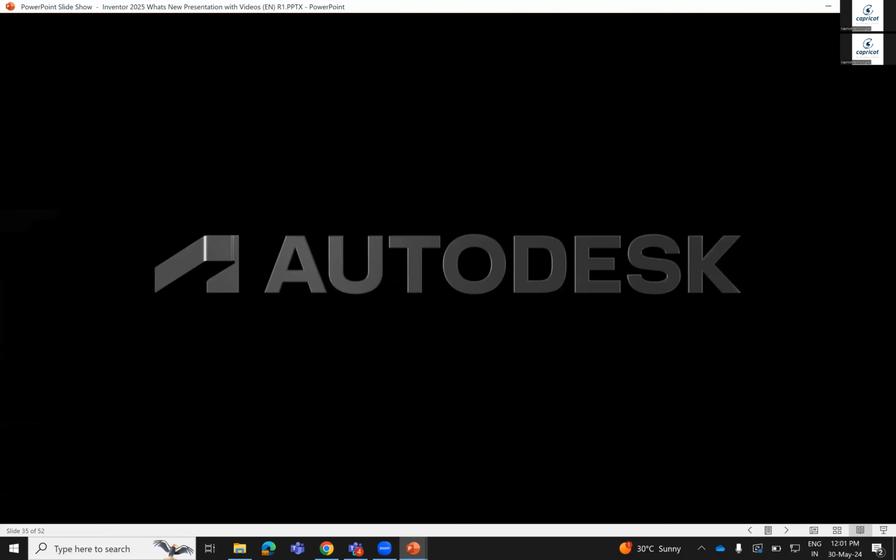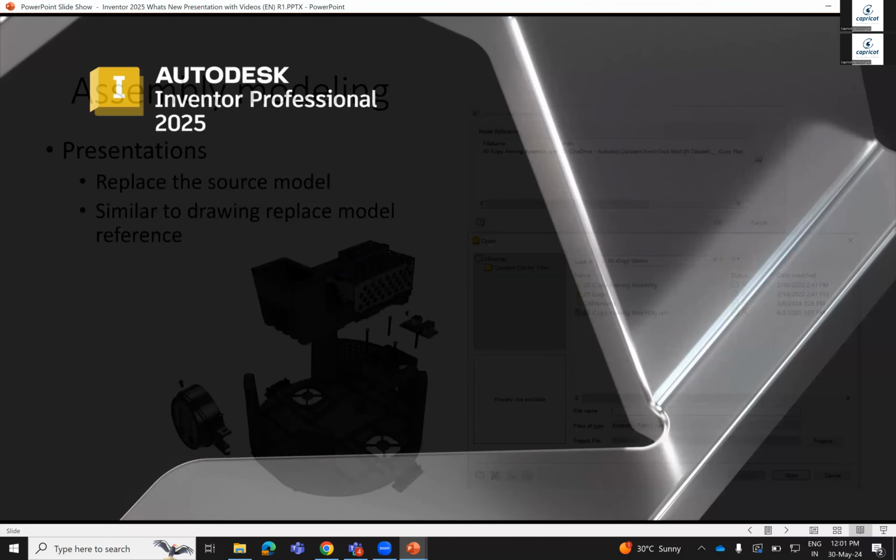It means all the solid bodies can be set to one color, sheet metal to one color, frameworks to one color. Okay, this is what color schemes tell you. By seeing the model itself, it happens sometimes in a larger assembly that I want to highlight all the components which are made in sheet metal. At that time, I can use this color scheme. Enhance our vision.